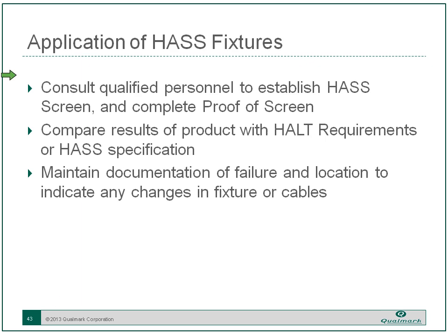The actual application, we'll sit down, figure out what you need to do for the HASS screen, do the proof of screen. Those are all topics for other webinars, but the creation of that screen is a critical piece of it. Make sure that what you're measuring on the product is, look at how it's happened in HALT, how it's happening in HASS, document everything. In HALT it's critical, and in HASS it's critical.